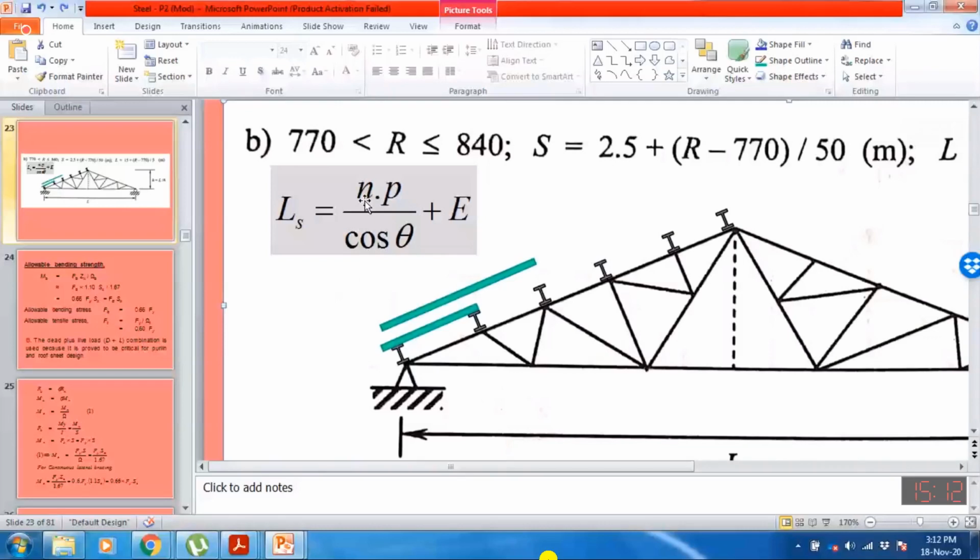If this distance is less than or equal to 4 meters, then instead of using one small sheet, I will use one larger sheet to cover the two consecutive panels, so I don't need to cut the sheet into smaller sizes. But if the length of the sheet required to cover two panels is more than 4 meters, then I cannot opt for this option.